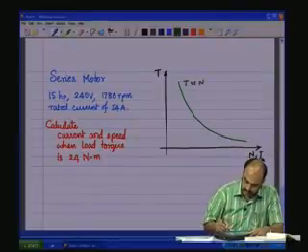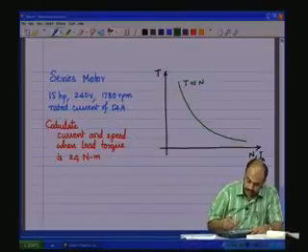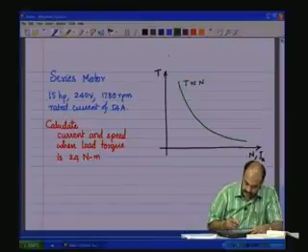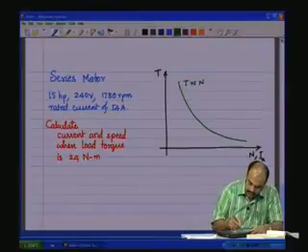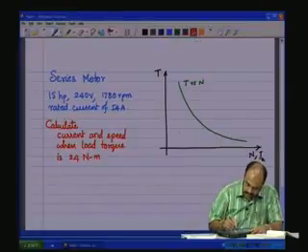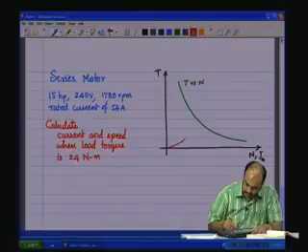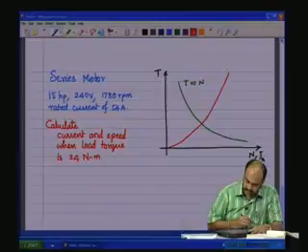As the speed is increasing, the torque is reducing, and at very low speeds the torque is going to be very high. And there is torque versus IA. When IA is equal to 0 it is like that, and then it is taking a square form because torque is proportional to IA square. So, it goes in this fashion.